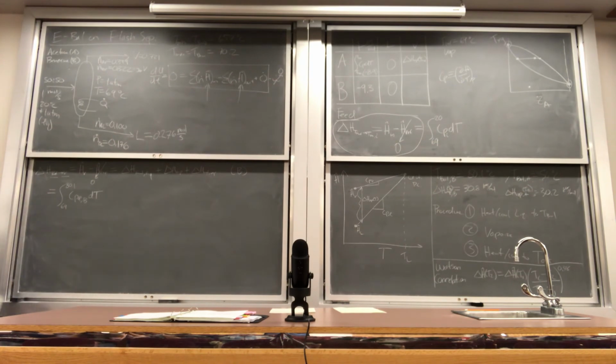And we're not assuming it's constant. If you did assume it was constant, you would have to decide, is it a constant of 69, is it a constant of 80, is it a constant in the middle, whatever the conditions are. If you did assume it was constant, you could just do CP times delta T. Correct. Couldn't you? Yep. But the reason why, oftentimes, if you build a good spreadsheet to do these calculations, just crunching the numbers to get a C sub P, if you're looking up out of the back of the book, is often a difficult enough task that integrating it isn't much more difficult.